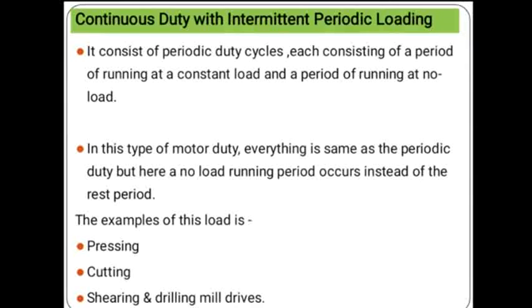That means in this type of motor duty, everything is the same as the periodic duty, but here a no load running period occurs instead of the rest period.